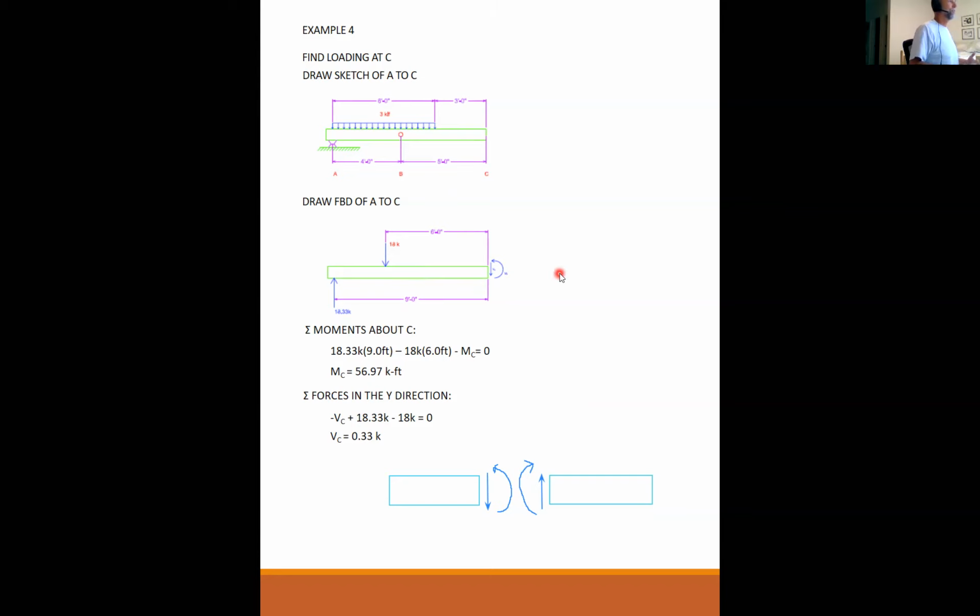And just for example, in a concrete beam, you have to put your rebar where the tension is. So if you think you have positive bending and you actually have negative bending, you're going to have a huge problem because all the rebar is going to be on the wrong side of the beam. So positive bending and negative bending are very important to distinguish. And you can only get positive and negative right if you use this sign convention.